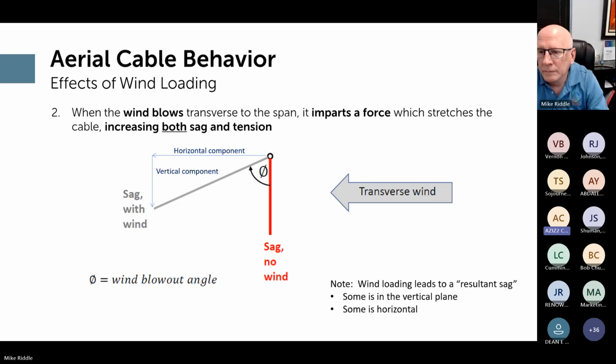What they were doing was marking the sag on the tower using line of sight. Then during the final stringing, where the horizontal suspension insulators were straight, they marked the conductor and clamped it, and at the end they dead-ended it using the last span. In this way, they were controlling it so there was no change in the sag. Well, it sounds like a very good process. Yeah, mhm.